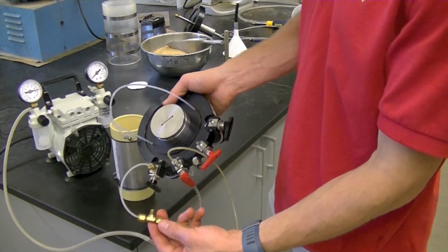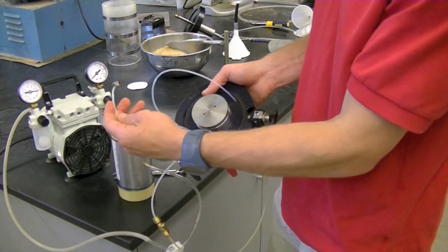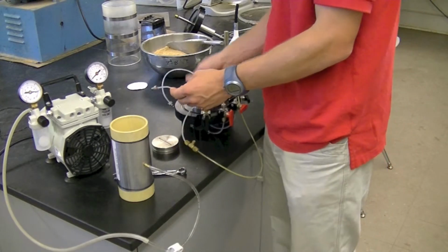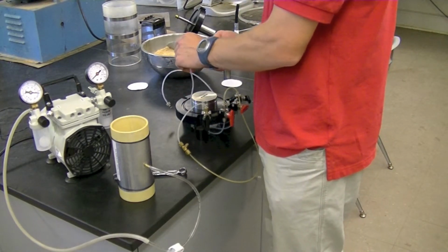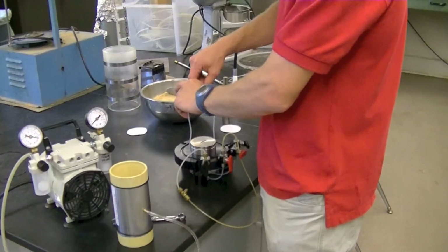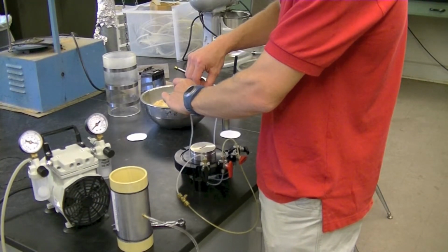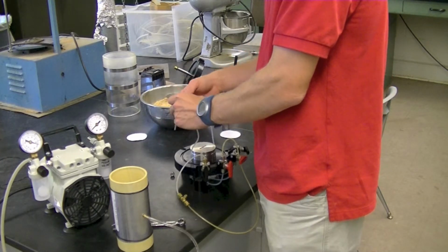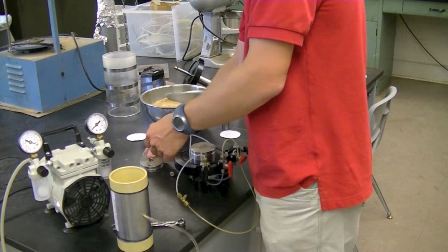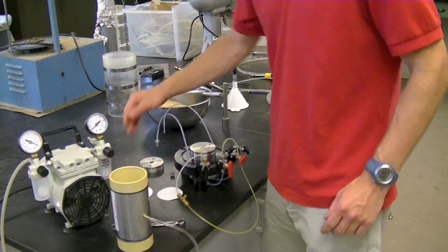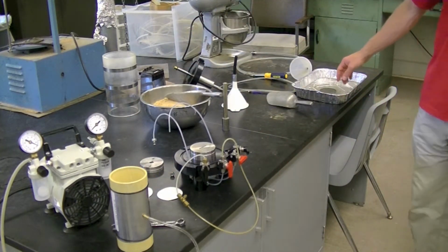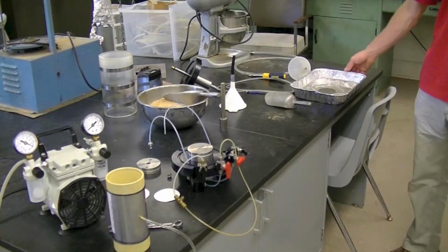The black and red nozzles on the left side of the base pedestal control the left top and bottom drainage lines. Notice the top and bottom are bridged for now. We will bridge the left top and bottom drainage lines during specimen molding to keep the dimensions consistent. The connect valve in between the two pairs of nozzles controls the cell pressure or pore water pressure.